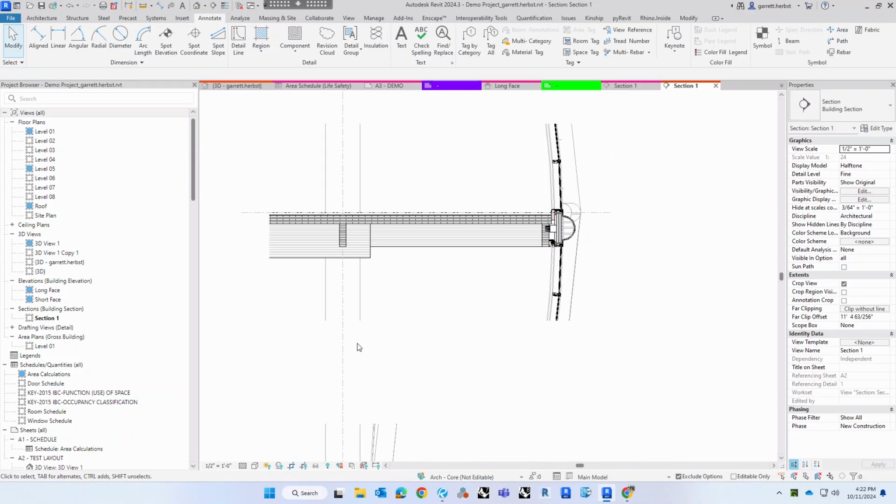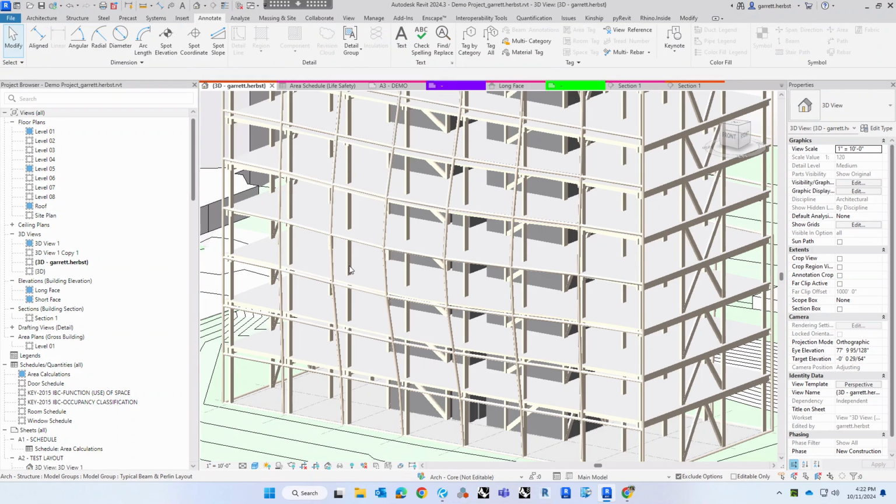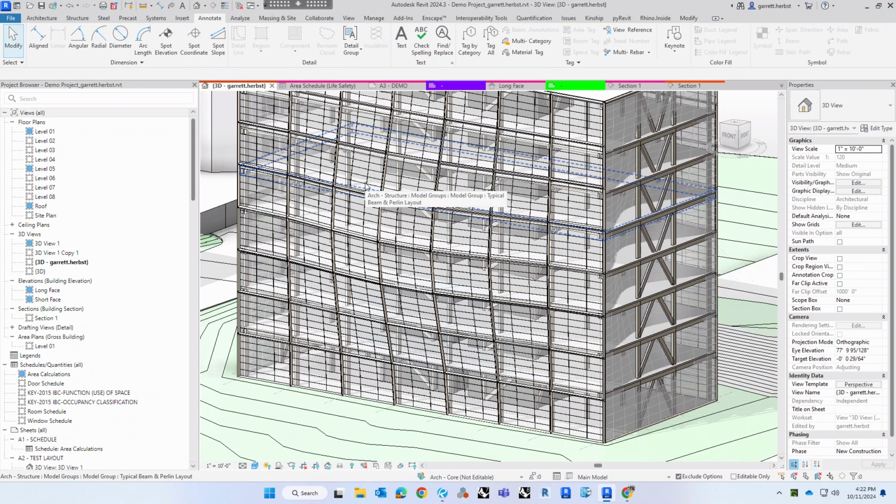Because this is the largest distance away from your primary column grid. At the base and at the top, you're really not worried. But to support that, you would really just want to take those beams all the way out. And then again, you would probably also brace it in some way diagonally to make sure it has stability. That's the type of detail that you've got to figure out.